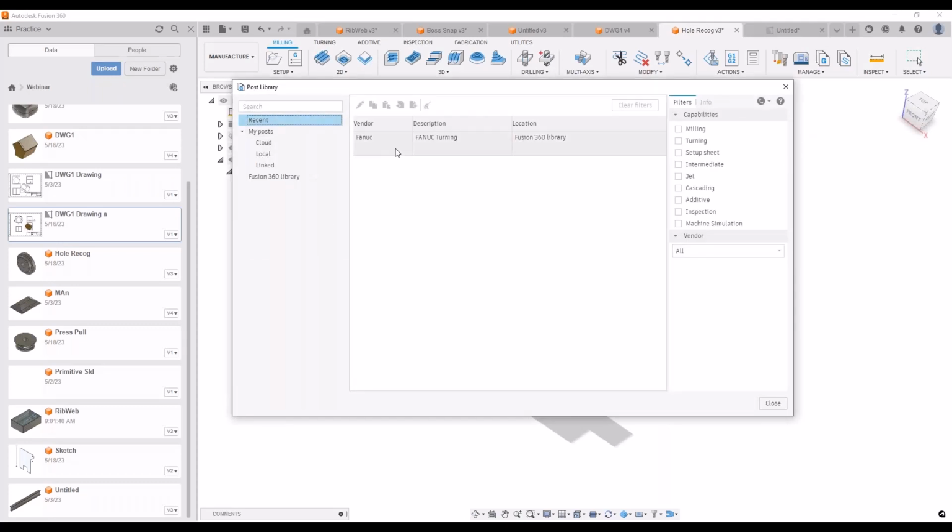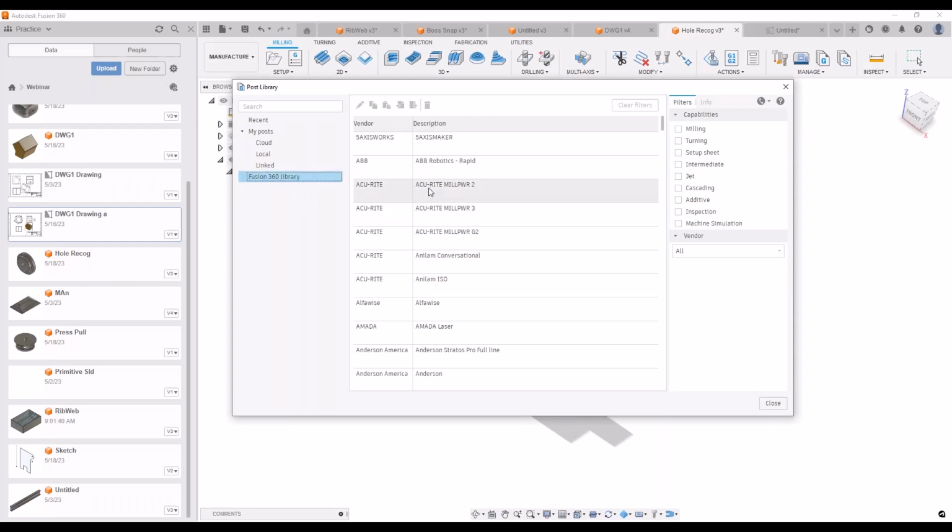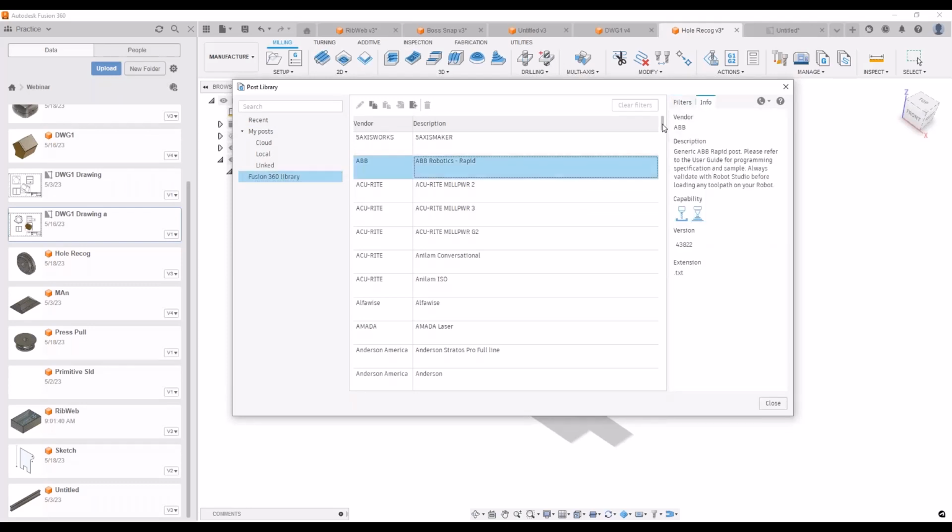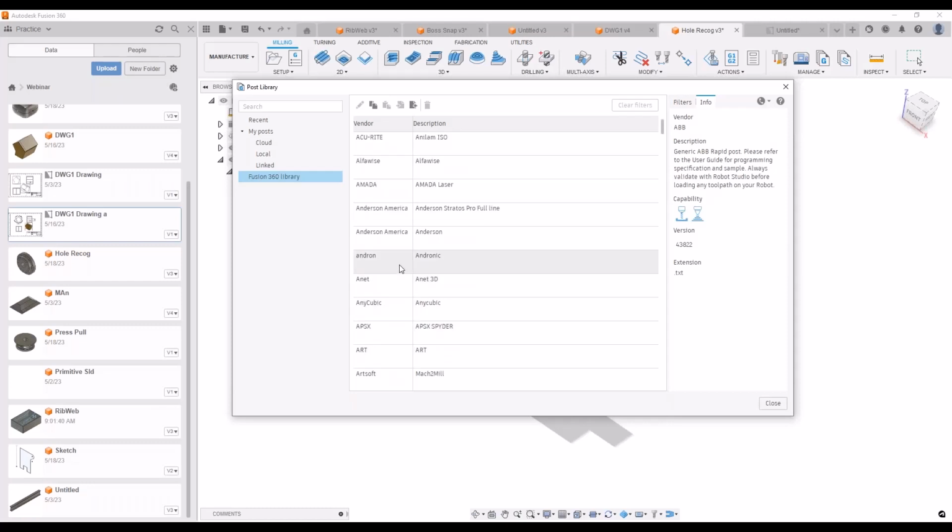Again, this is the one that I've recently used, but if you look at the Fusion 360 library online, all of these are available. Got everything from 5-axis works, you name it, almost it's there. Got a large list of them. You've got Autodesk ones that are standard. There's a few you can get to the Fanuc. There's a bunch of Haas ones as well that you can use. So there's a large list of post processes that you can use, and if you don't find it, you'll most probably also be able to find it online. And also the post processor or your G-code that's generated by your CNC generation can also be modified to suit any specific machine that you may have.